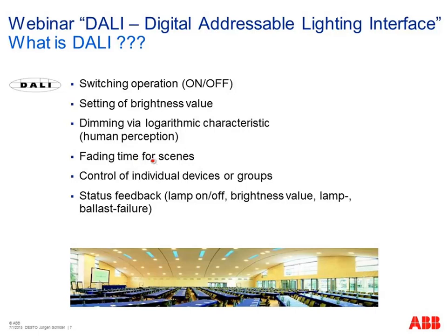In a DALI system, we can control individual lights. Each lamp in principle is controllable, but you can also create any groups. And these groups can be changed later on. So one big advantage is additionally the flexibility. With any hardwired system like 1 to 10 volt, it's not possible, or only with rewiring. Here it's much easier together with DALI technology behind.